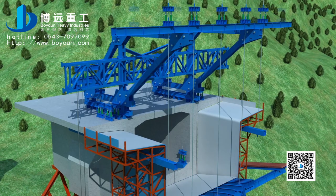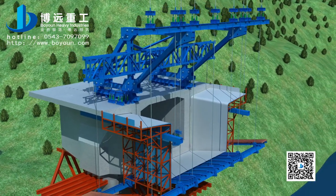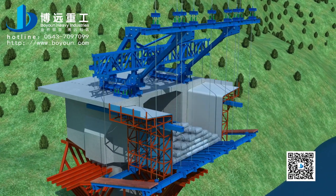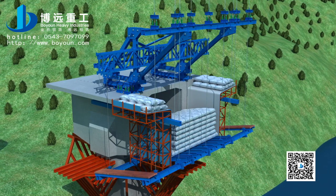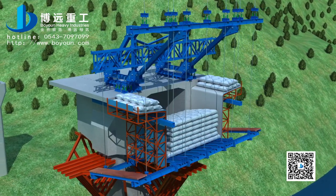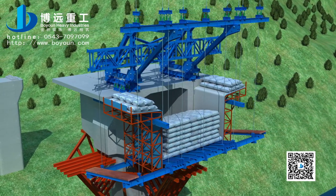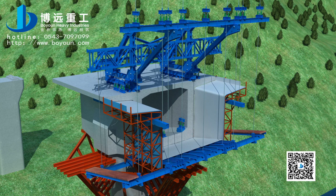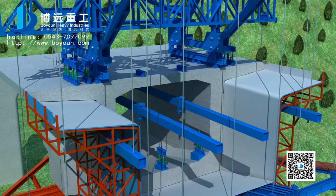Review the drawings and adjust various parts of the forming traveler again to the designed place. Pre-press the hanging basket structure according to the pre-press scheme. Compare the pre-press monitoring data with the Midas modeling stress data and ensure they remain consistent. Adjust the bottom elevation of the forming traveler. Install and fix the internal nose girder.